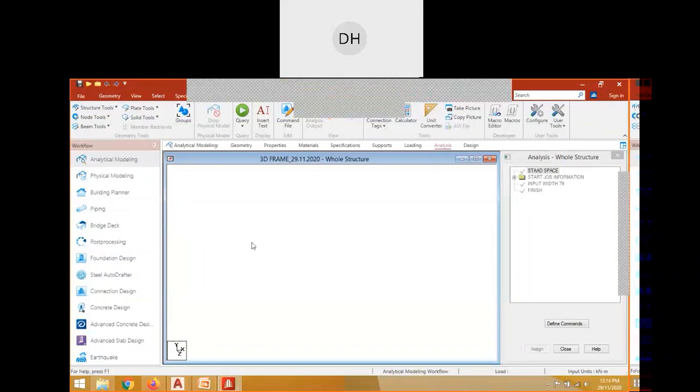Before analysis, it will tell you everything, whether your model is correct or not. If you ask me about other software like ETABS and others, there only after analysis will you get the report, and then you have to interpret whether your modeling is correct or not. Of course, there are certain options available like animations, or you can go into the editor where you can check the errors. But here, if something is wrong, you immediately get the error, right?